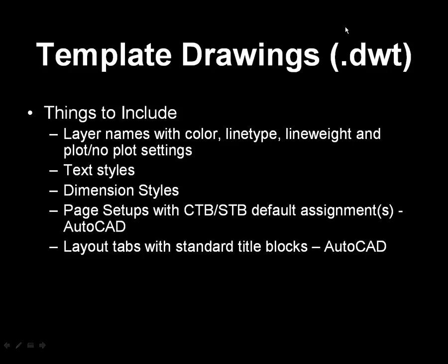And then something that I work with my customers and clients is setting out a layout tab with your standard title blocks in your template drawing. This is something a lot of people don't do. It's becoming a little more common, and maybe we can talk about that in a future session. You may have a layout tab in your template drawing for an 8.5 by 11 sheet, for an 11 by 17, for 24 by 36. You can have them set up differently, landscape and portrait. So there's a lot of things you can do, and then start drawings using those tabs.